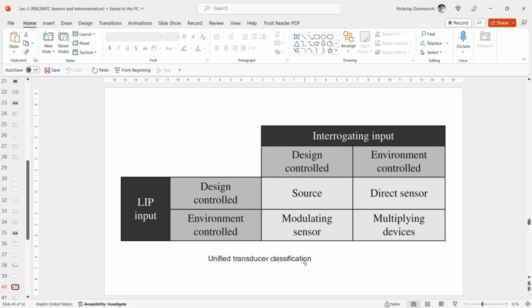The third, very popular nowadays sensor is a Hall sensor. The measurand is, in this case, a magnetic induction field, which acts on moving charges imposed by a fixed or known current applied to the interrogated input. Yes, we will be studying Hall sensors in more detail too.